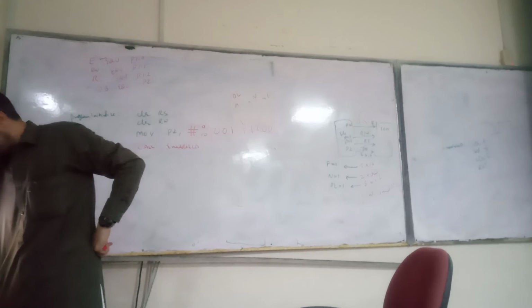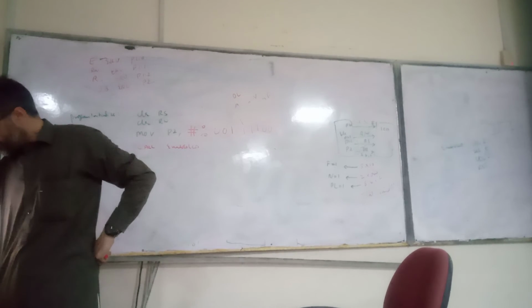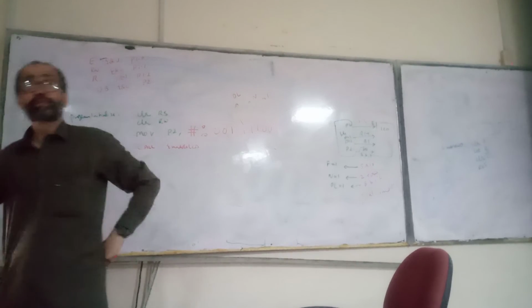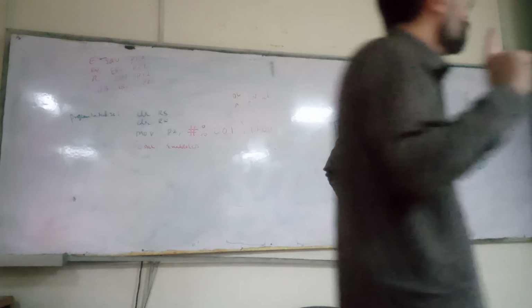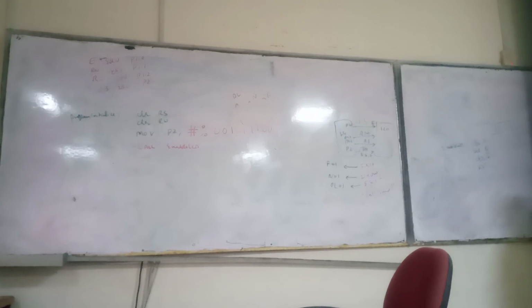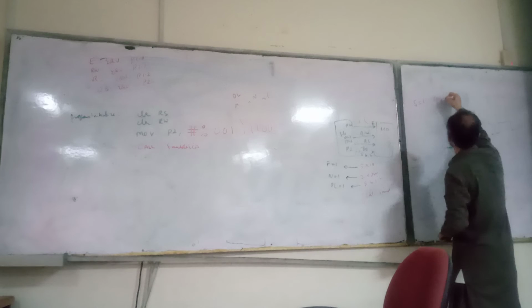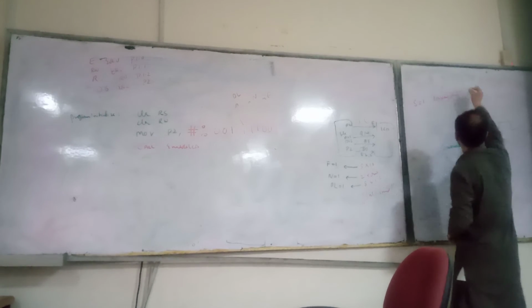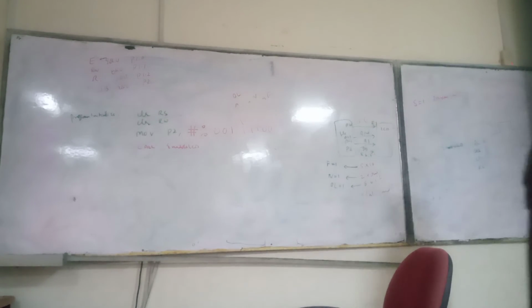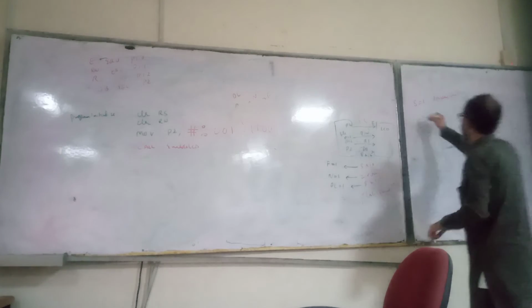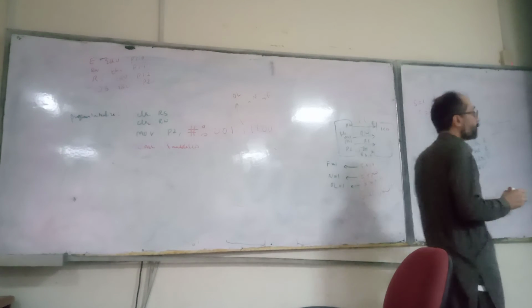Actually, before this you should also say that whenever some data is displayed, the cursor should move to the right with display shift. S is equal to 1 with display shift. So S should be 1 with display shift, and to move to the right, ID is equal to 0. Where are these lines? S is equal to 1 and ID.